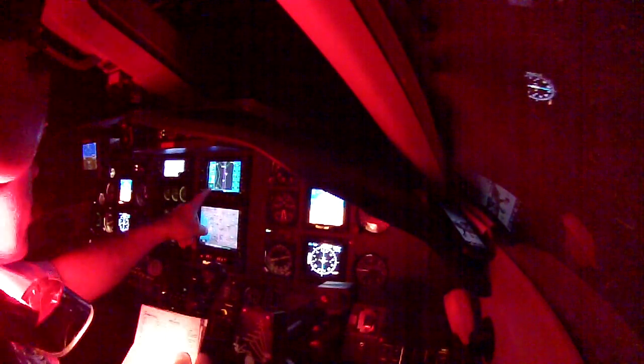So you'll see here, it says en route? Yep. On the Garmin it will say LPV. When it says LPV, you have localizer performance with vertical guidance. It's like an ILS approach. And when you look at the instrument approach procedure, which is, let's open it up, GPS approach, runway 5. You look at the minimums, we have LPV decision altitude of 291, which is 300 feet and half a mile.